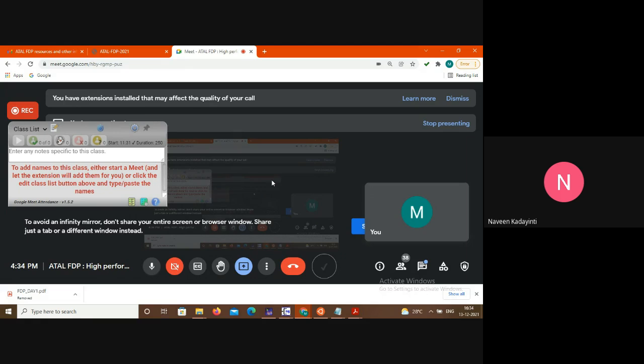These are simple things, for example, change the capacitance and see what happens, remove the zero cancelling resistor and see what happens, and simulate and try. We have tried to give as detailed write-ups as possible for you to simulate the netlists and circuits yourselves. We hope you will take the effort and simulate them. If you have any questions, we are always here, and we will try our best to address and solve your difficulties, whatever you may have.